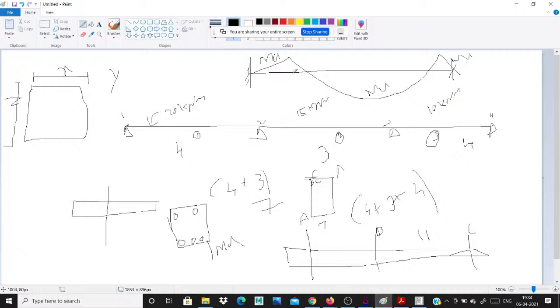So you provide the side bars and do not need extra bars, right? The tension zone has no moment, so do not need extra bars. You provide the main bars also, but in the tension zone where moment is high, you provide the extra bars, right? This is the B section, the B cross section, right?